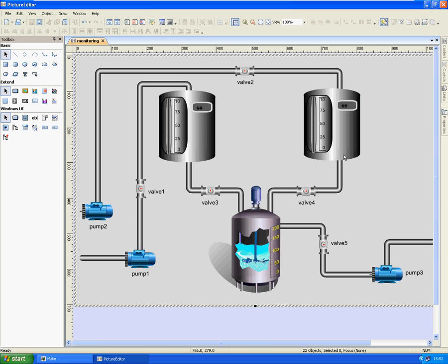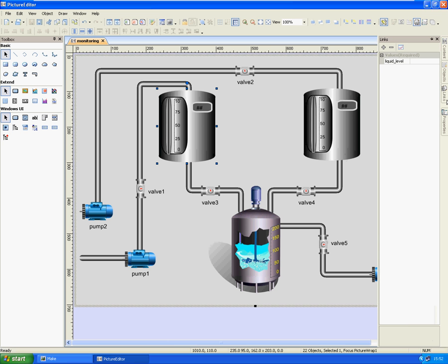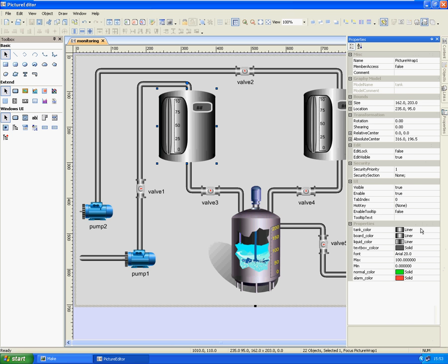Configure graphic elements. We set the elements according to what is needed in the project. First, set the raw material tank. Choose the model object and modify the properties in the Properties window. We can set these properties by clicking the button. Properties configuration of the catalyst tank is similar to the raw material tank.